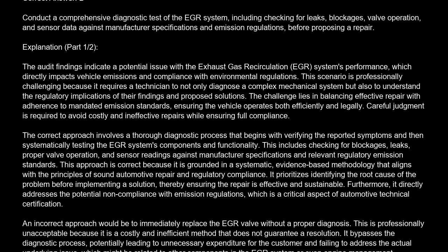It prioritizes identifying the root cause of the problem before implementing a solution, thereby ensuring the repair is effective and sustainable. Furthermore, it directly addresses the potential noncompliance with emission regulations, which is a critical aspect of automotive technical certification. An incorrect approach would be to immediately replace the EGR valve without a proper diagnosis. This is professionally unacceptable because it is a costly and inefficient method that does not guarantee a resolution.